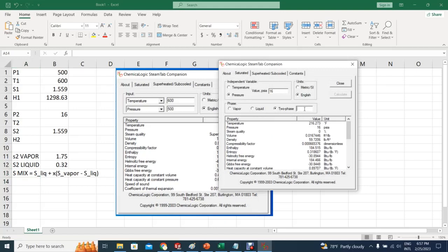You can guess, you can start to mess around with it. Like, for example, let's say that's 0.8. Calculate. Well, 1.46. We need to hit the 1.55. So let's have about 0.9. Calculate. It's above 1.60. I need 1.55. So you can see that it's between 0.9, maximum 0.8. It's a number between here that will make the exit entropy from the expansion engine the same value as the input.